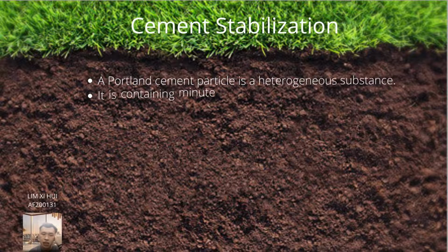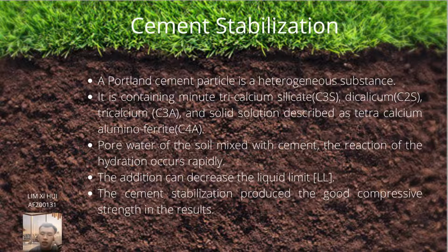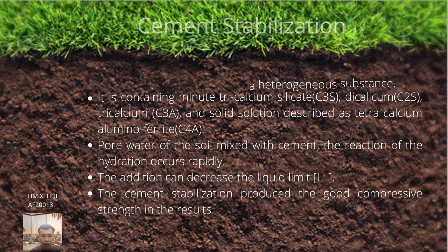The second is cement stabilization. The pore water of the soil mixed with cement, and the reaction of hydration occurs rapidly. The addition can reduce the liquid limit, and cement stabilization produces good compressive strength as a result.